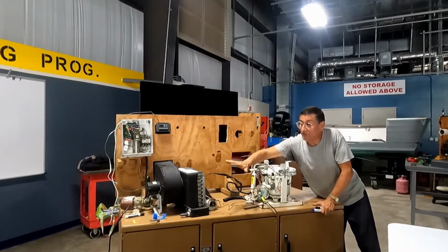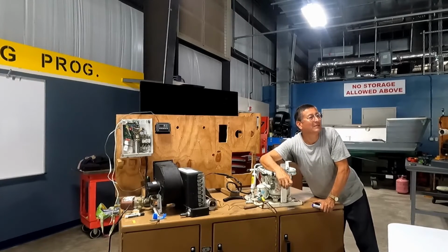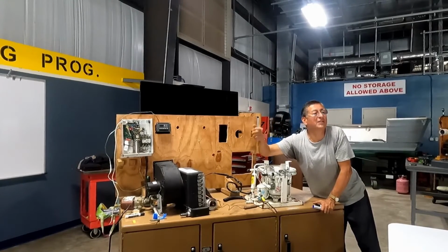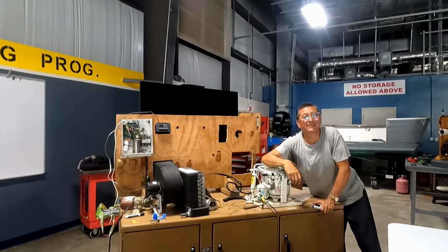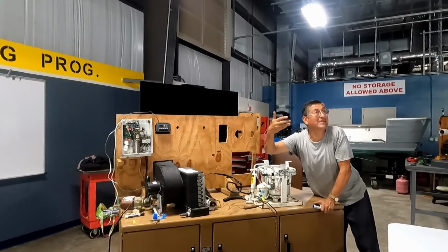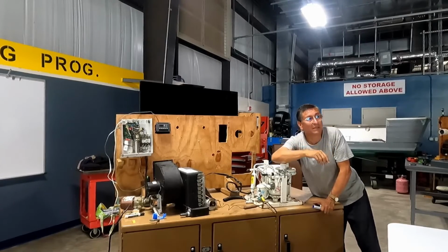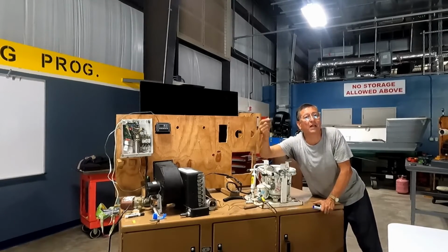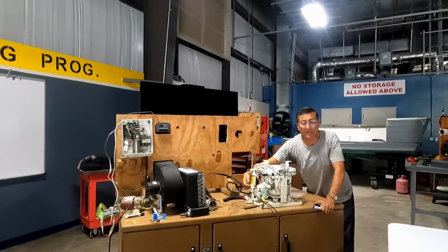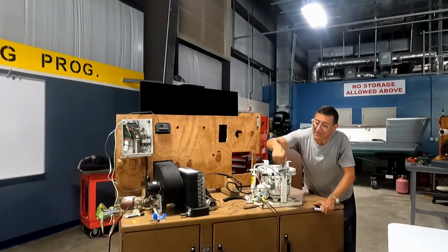It's evaporated, but if you touch those pipes, they are too cold. Not frozen, but too cold. And the refrigerant is boiling because the pipes are surrounded by ambient air. You remember? The refrigerant normally boils at -2 degrees. Right now at this ambient temperature, it's boiling. But it's boiling for him. For you and me, when you touch those pipes, they are too cold. It's completely vapor, and returns here and enters the compressor as vapor. And once again it is compressed, and once again it is sent out.